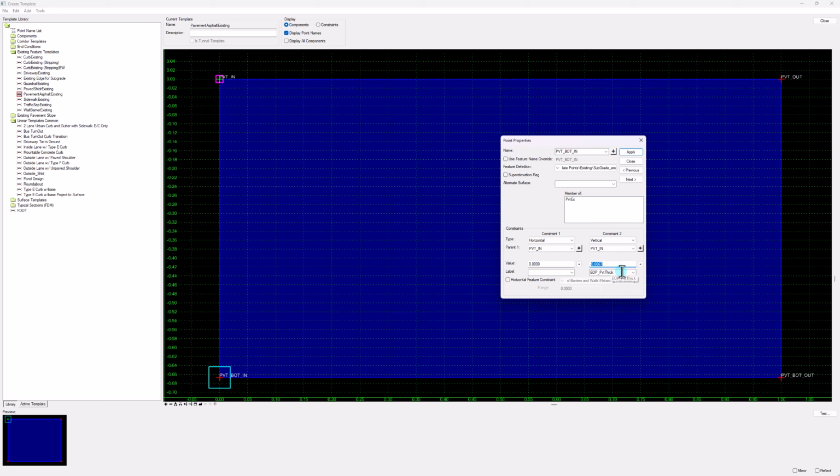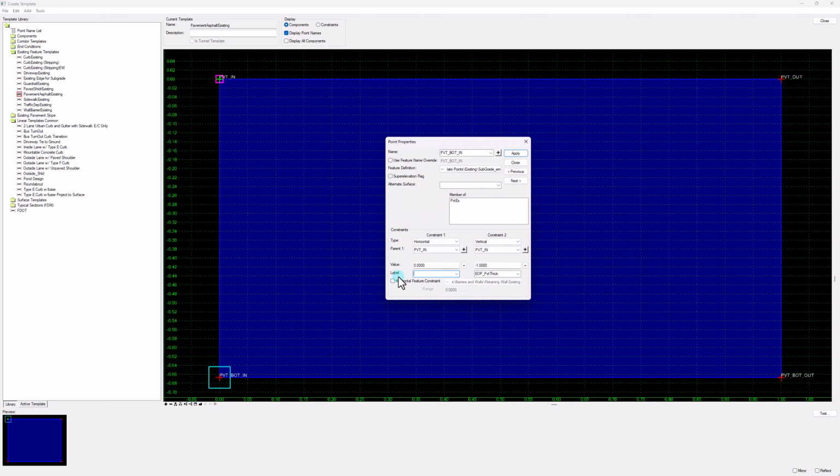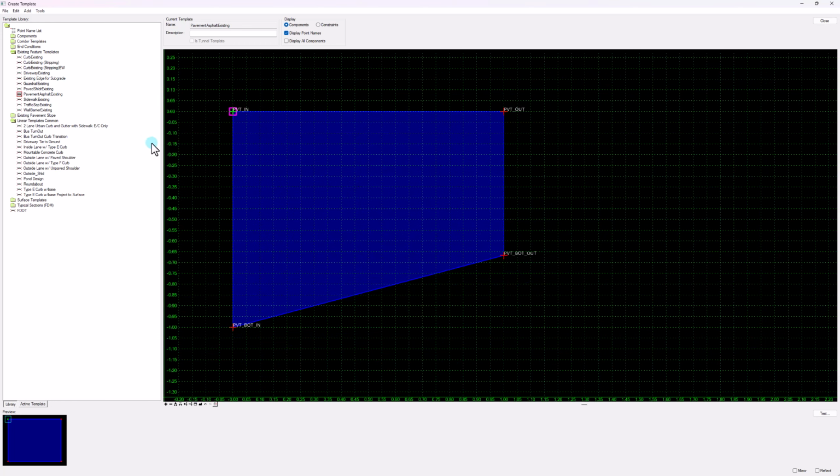So for now, for an example, I'm just going to say that my total thickness is 1 foot, which is pretty typical. I know I have a project that maybe it's 13 inches or something like that. But what this label allows you to do is go in there and modify this depth based on the situation. So maybe this road that we're doing right now is a foot, but the other road that goes off towards the top of the screen, maybe that's 14 inches or something like that. So you could come in here and change that, and we'll show you how to do that in a second. So let's just save that, and you'll see that the template drops down and only one side dropped down.